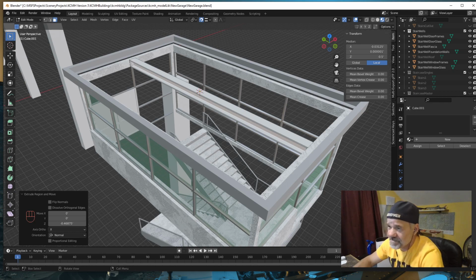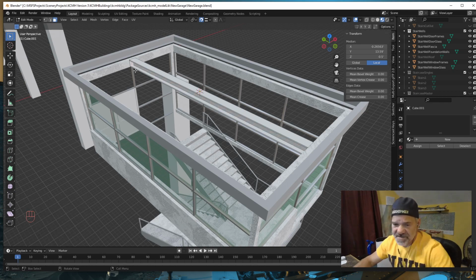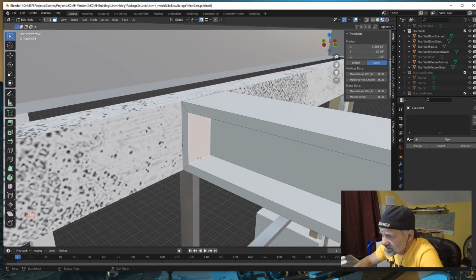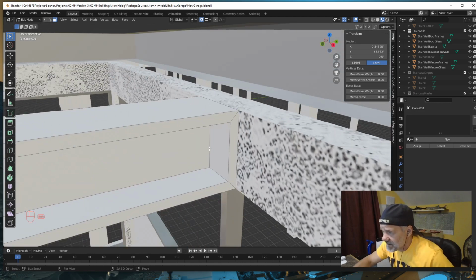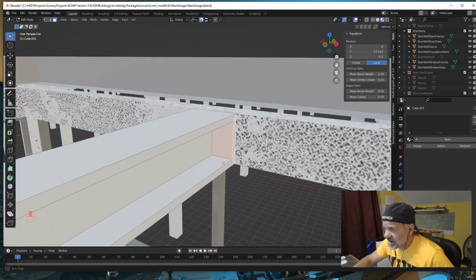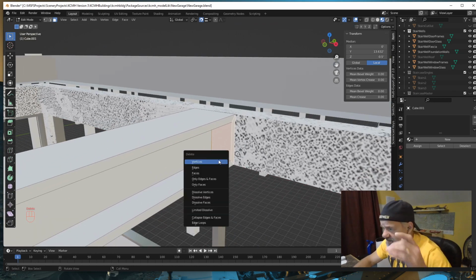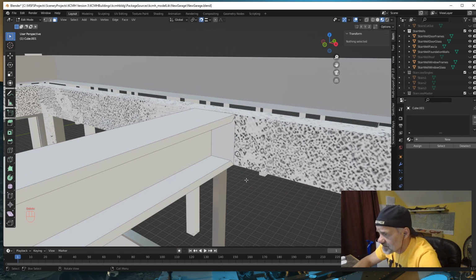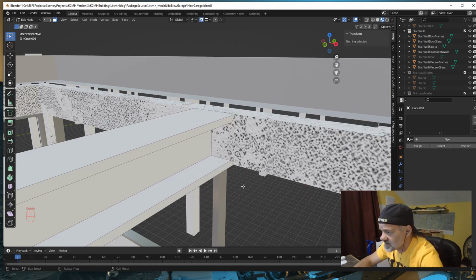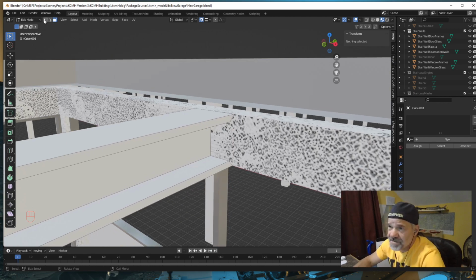Now, at the end, this polygon right here, so let's select this polygon and zoom in. We have to do some edits, so I'm going to hit period on my keypad. And what I'm going to do is simply select this face, shift, this face, this face, this face. All right. And I am going to delete faces. Now I need to get rid of this face. Delete faces.